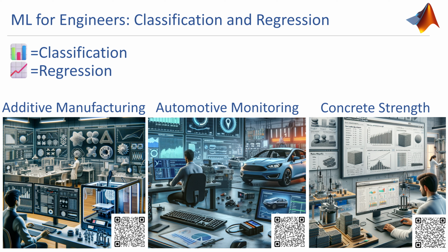This case study is unique because you collect your own data with an OBD2 connection to an automobile. And what you do is you analyze automobile performance, such as catalyst heat-up rate, where you activate the catalyst. There are also some other regressions in there to be able to predict fuel economy versus speed. And so you can do a lot with this data.